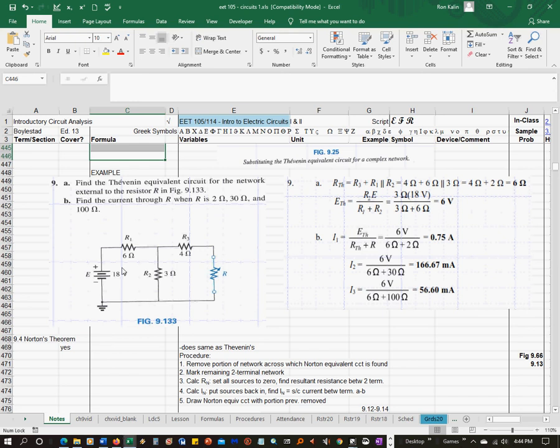E Thevenin: you put this back in the circuit. And remember, this is an open circuit here, okay? So you're measuring the voltage across this open circuit. Since no current is flowing through R3 because this is open, then the equivalent E Thevenin voltage ends up being the voltage across R2.